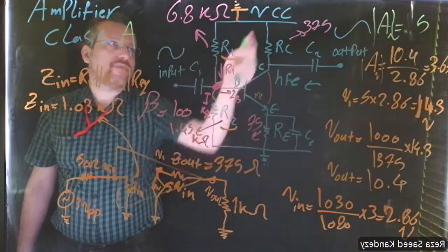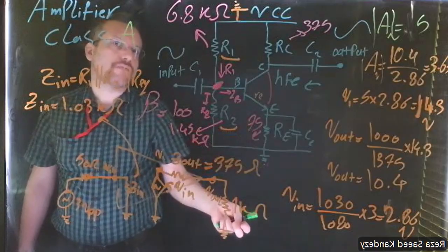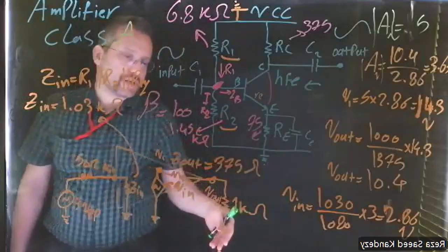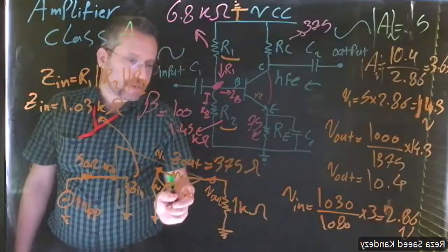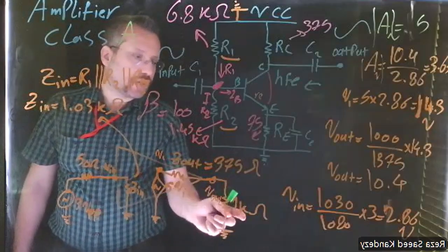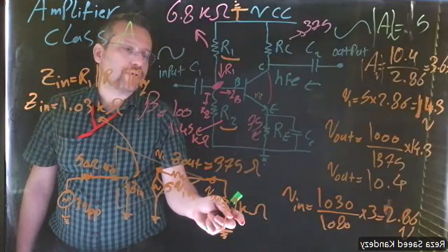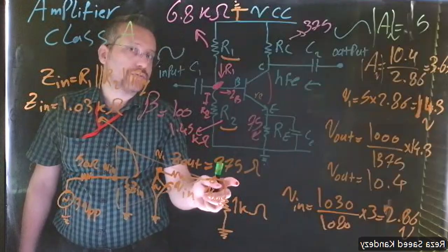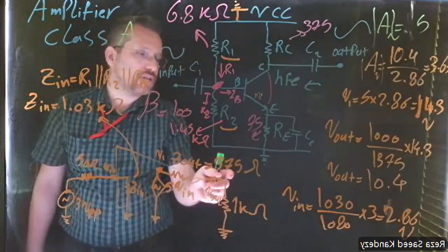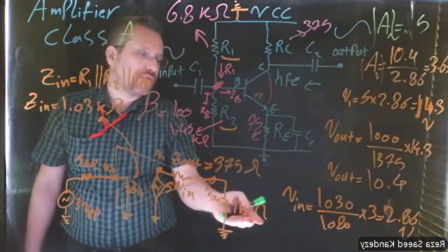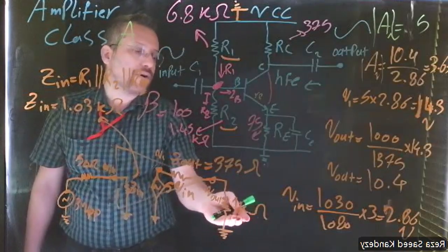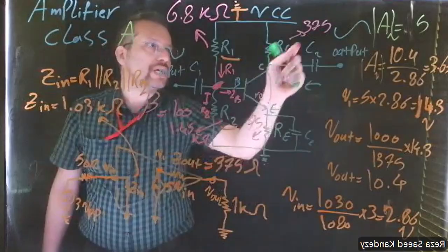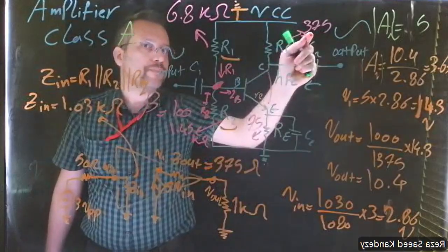Okay, now, as I said, in our case, we consider the gain, the collector current, and the VCC as our input for the design. Sometimes you need impedance matching. So you need that Z out to be equal to your load, and that way you have to start with Z out. That means Z out is RC. So, for example, if we need 1K as our load and we want impedance matching, our RC would become 1K.